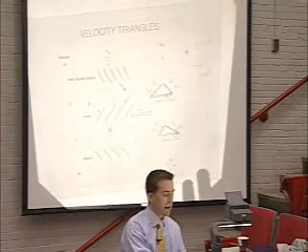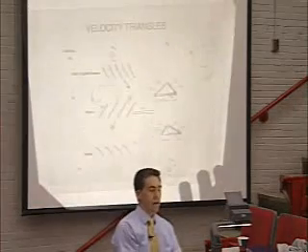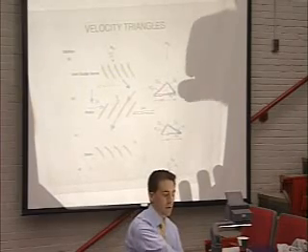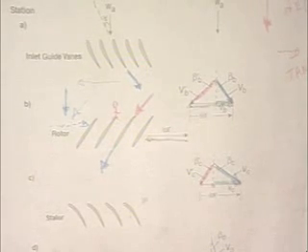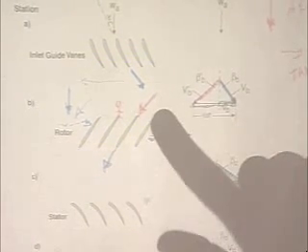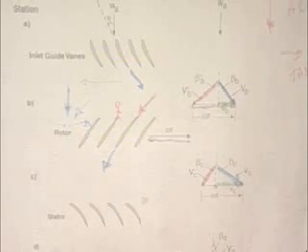So this is complicated. You're going to work a problem on this in a moment. Let me just go through the steps again. You assume the flow leaves the trailing edge at the trailing edge angle. So that gives you this vector. Basically, this flow is turned or added some swirl, but since it's not moving, it's not done any work. It's just converted internal energy to kinetic energy. I then put myself in the reference frame of the moving blade by subtracting its velocity, and that gives me the red vector, which the person on the blade would see. I then say, well, the flow will always leave this blade attached to the blade at the trailing edge angle. So that blue vector then, which I should have drawn as red here in the relative frame, I'll draw it on this one.